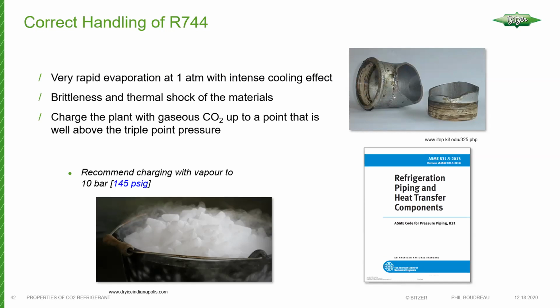What we have to be careful with is, when charging systems, that certainly you can form dry ice, which we never want to do. You always want to charge up the system to some static pressure using vapor. So for example, 10 bar or approximately 145, 150 PSI. And if you think about the triple point, 75 PSI, so we're pretty much doubling that pressure to make sure we're well above the triple point before we start charging any liquid into the receiver of that system.